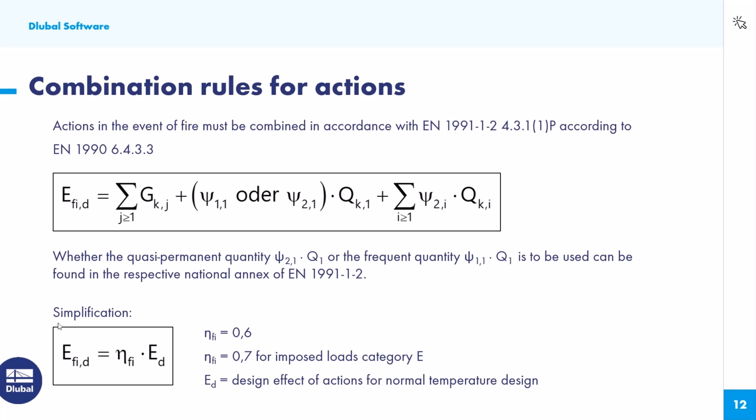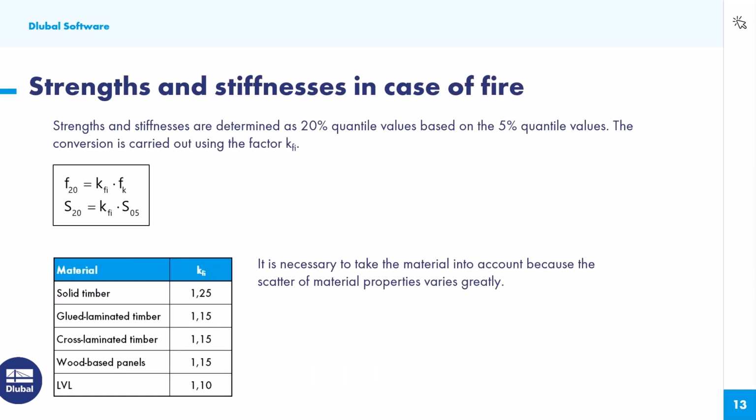Okay, so there's also this simplification where you use the internal forces or the actions from the normal temperature design multiplied by some factor, and you can design with these internal forces, but I do not recommend using this simplification since it is mostly way too uneconomic. All right.